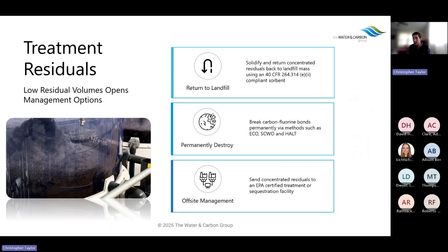Although there are landfills out there adding just the leachate back directly in as liquid. In fact, we were doing that before we fine-tuned our organoclay at the Bethlehem landfill site. And there is some pretty good data on sequestration, but I do know that there are a lot of landfills that are uncomfortable with just the premise of bringing it back into the working phase as a liquid in general, right? And I can completely understand why. But that is something that you can do. If that's not something you're interested in doing, then permit destruction is another option as well.